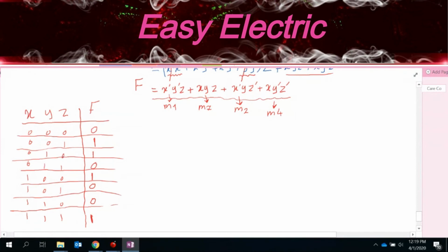So here we have the odd number of 1s. We have 1 between 3, right? So that's odd, so it actually gives us 1. Here you have 2, 1, which is an even number, so it's got the 0, right? So that means it's able to just detect the odd number of 1s.